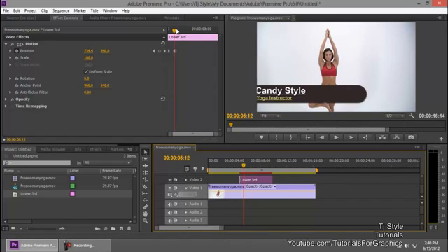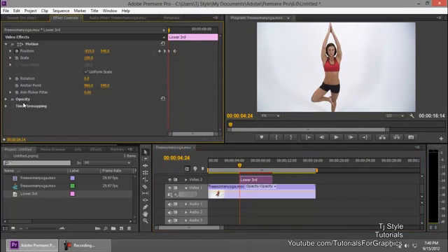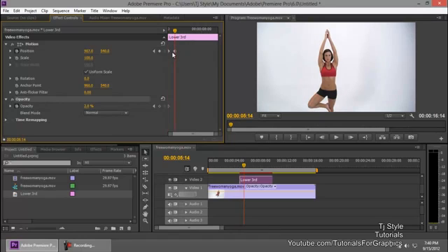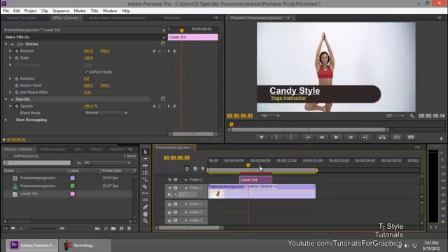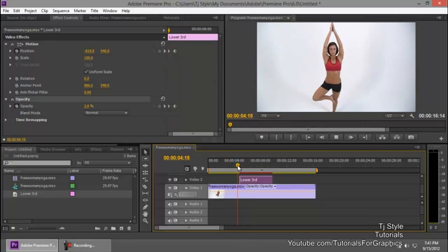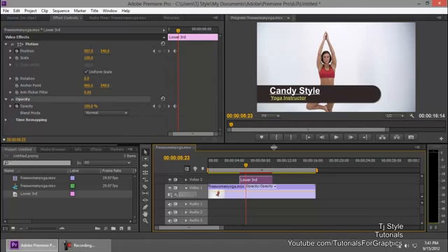And I think guys that an opacity parameter won't hurt, so I'm going to add a little bit of opacity changes too. So select your opacity parameter, go to 0, then guys hold on the shift key, go to the next keyframe and add 100. So you'll see a good enough animation happening. See this? Okay, that took a little bit of time to load. You see that it looks good now.